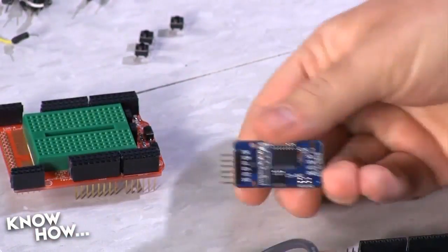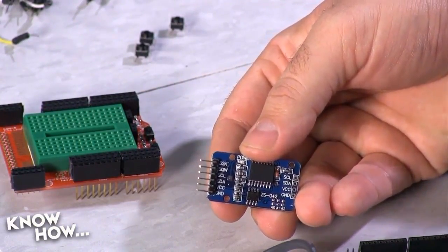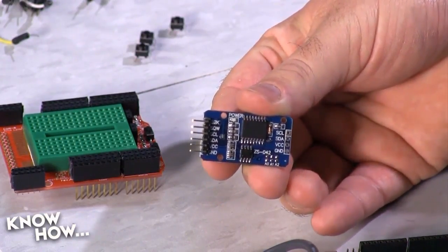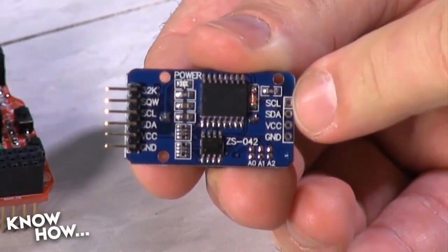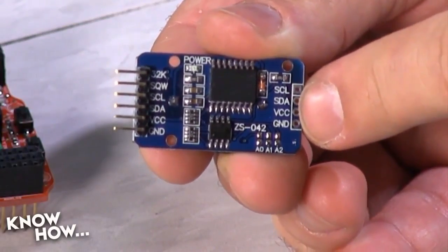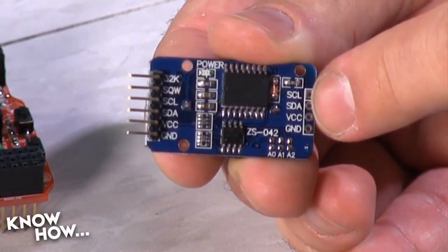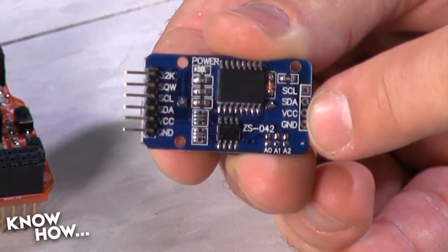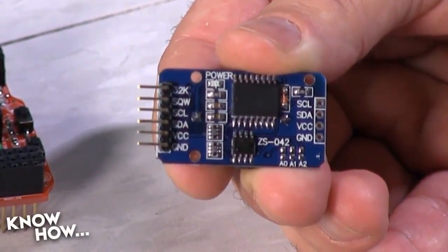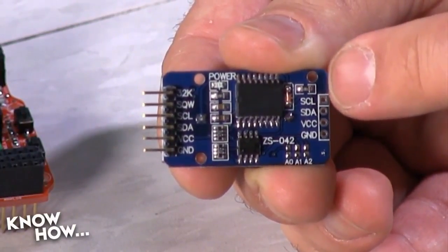The real-time clock uses a protocol called I2C, or IIC. I have no idea what it stands for. I used to know that. It's a proper noun now. It's I2C. It is a serial bus. You see over here where it says SCL and SDA. That stands for serial clock and serial data. Those are where the actual data is exchanged between the real-time clock and the Arduino. And then VCC is your power source, and ground is your negative power source. So those 4 pins are all you need to get the data into and out of this real-time clock.